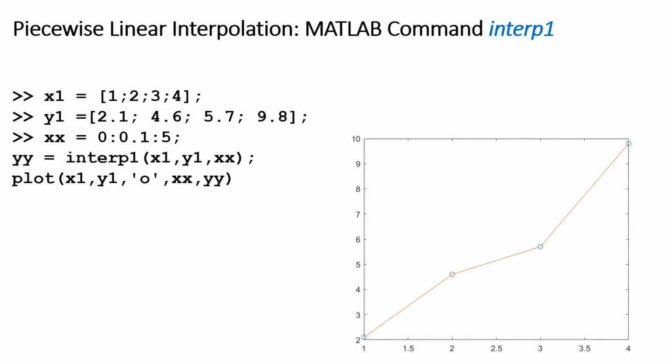There are other ways of interpolation in MATLAB, especially when you have to fit your function through many data points. Here, the one-dimensional piecewise linear interpolation built-in command is shown. The same data points x and y are used here, and interp1, which refers to one-dimensional interpolation, is used.